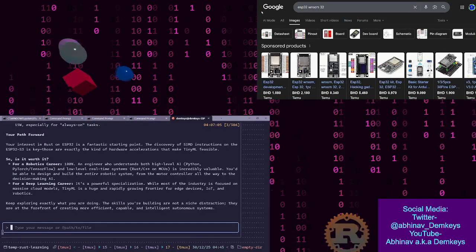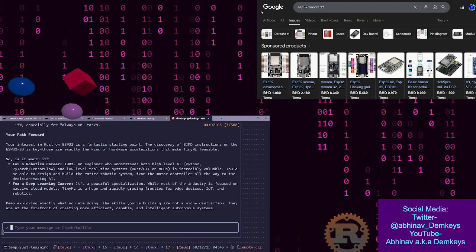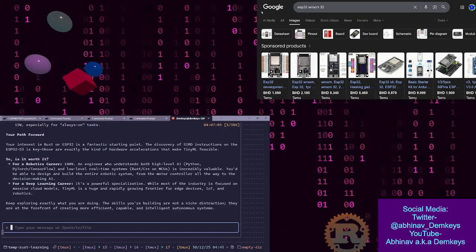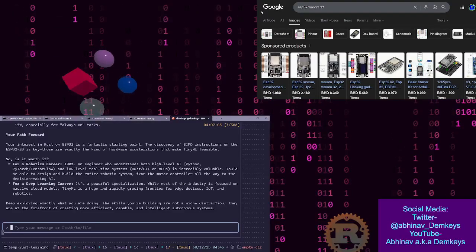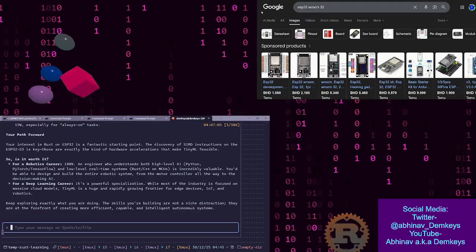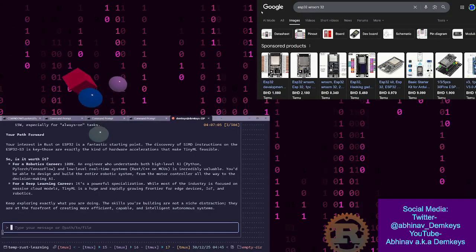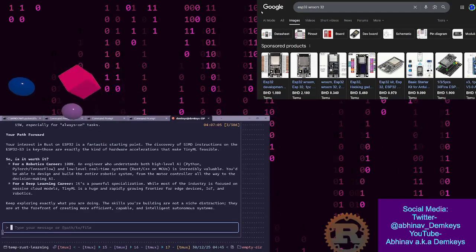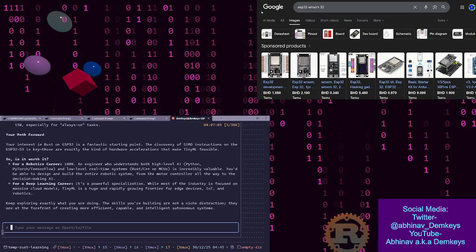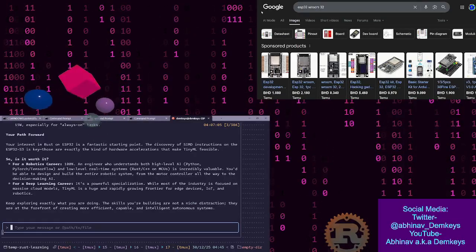Yeah. Running at 240 megahertz constantly will warm the chip. I should test that out actually, in a safe way. But yeah, I should test that out. Poor voltage regulation: on cheap boards, the voltage regulator next to the ESP32 chip can get hot and transfer that heat to the MCU.